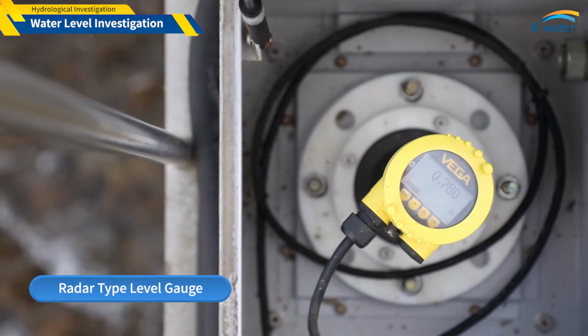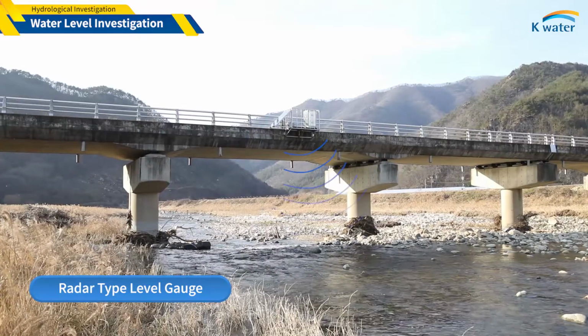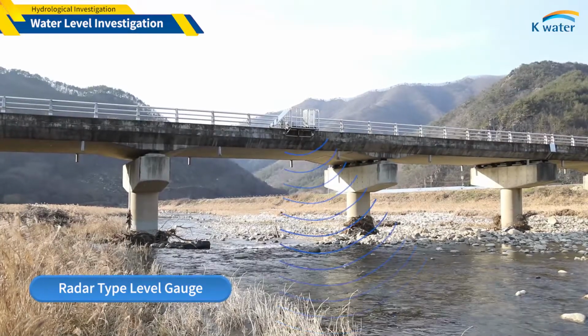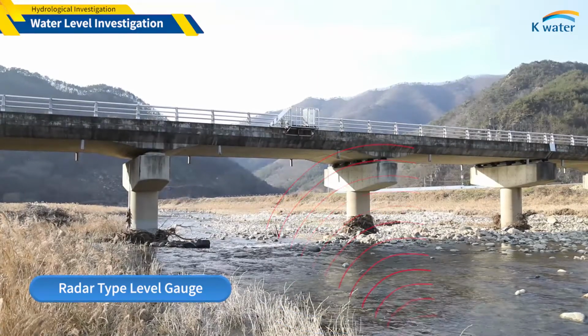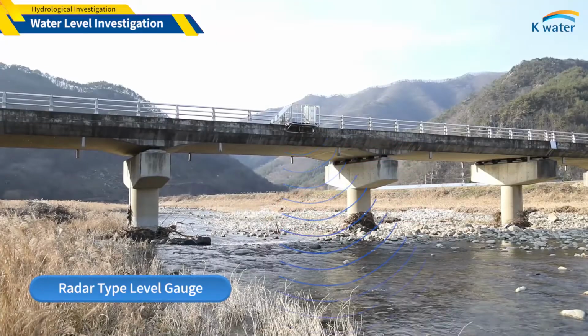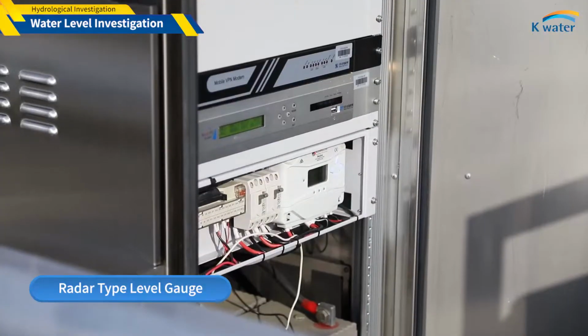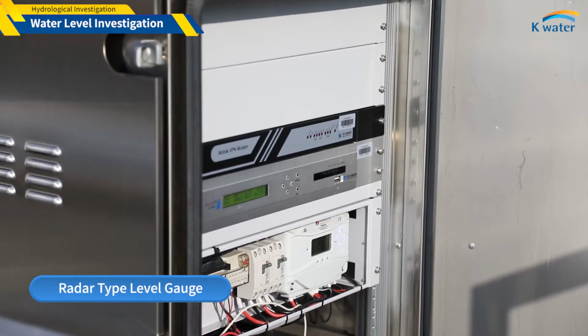The radar-type level gauge measures the water level as follows. Microwaves from the electromagnetic generator are transmitted by the antenna system of the radar sensor to the measured water, reflected by the water surface, and received back by the antenna system. The time from emission to reception of the signals is proportional to the water level.